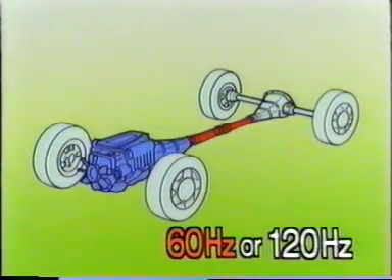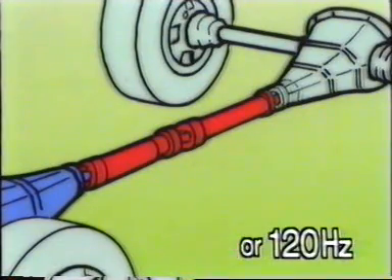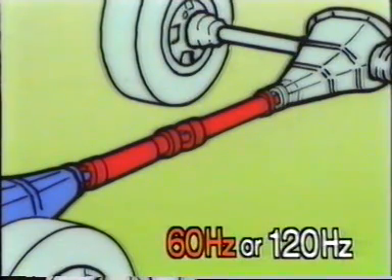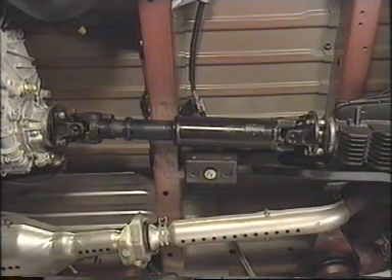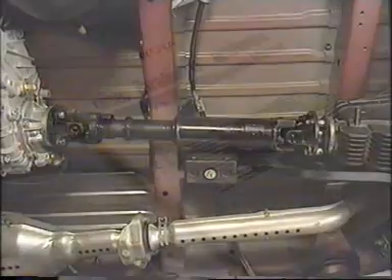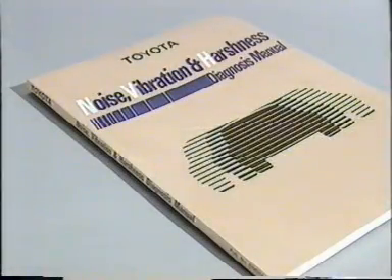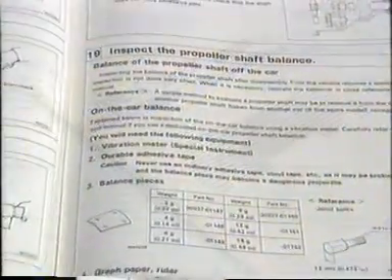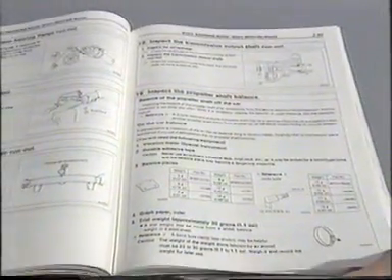We will now return to the case of the booming about which the customer complained. It appears that the noise is caused by something that rotates at the same speed as the propeller shaft. Or perhaps it is caused by the propeller shaft itself. We will check the balance of the propeller shaft, as it seems the most likely cause of the vibration. Please look in the NVH diagnosis manual to find the detailed inspection method to be used.